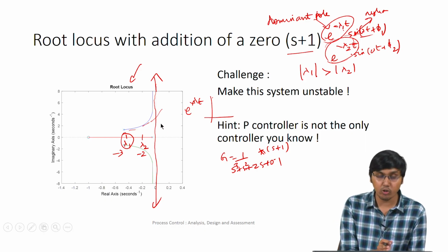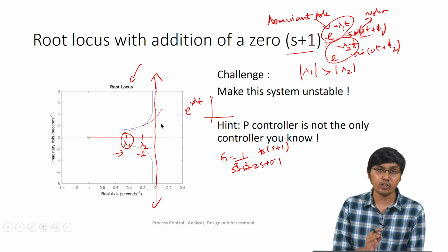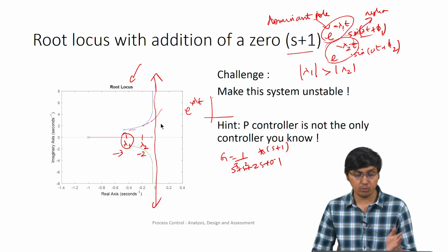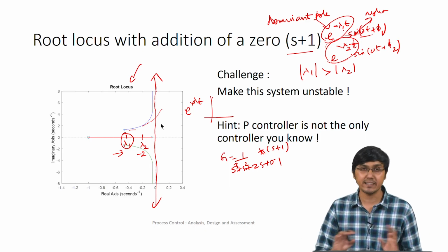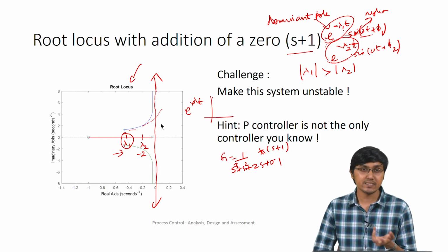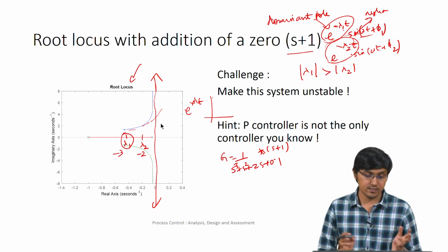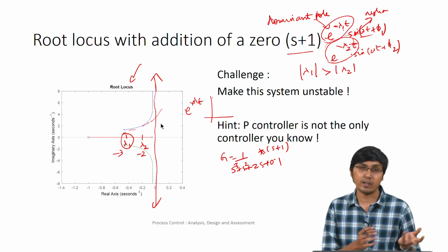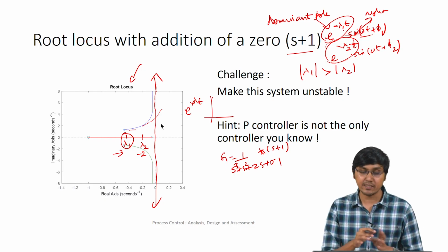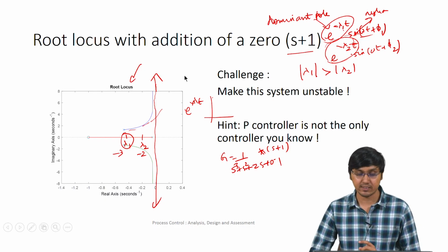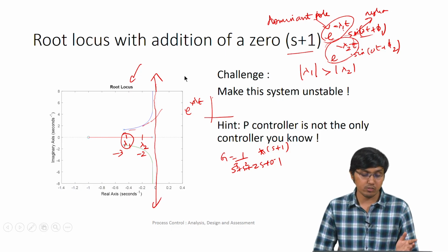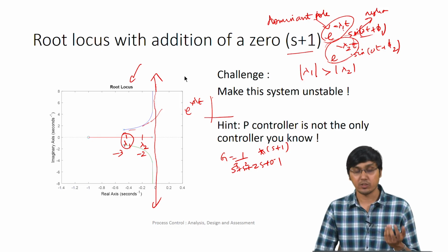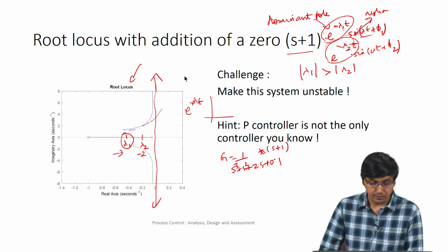The poles that are closer to the imaginary axis are going to have a bigger impact. So poles that are closer to the imaginary axis are called dominant poles. You can just remember these terms; you may hear someone talking about them. You should not think this is something new. It is very easy to observe when we do the partial fraction expansion. If you want to understand it more, just take some lambda 1 value and lambda 2 value, and then see the response of the system.